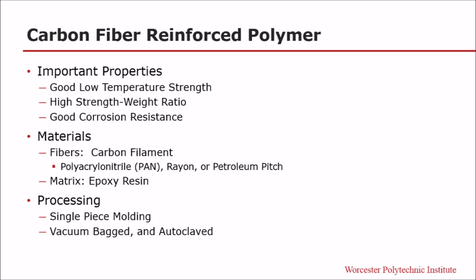They are usually taken and spun into filament yarns where they are chemically and mechanically treated in order to align all the polymers. They're then spun into yarns where they are able to be heat treated so that only the carbon atoms remain. This is known as a process called carbonization, where they're then able to be stored and further heat treated in unidirectional sheets that are able to be used in the composite. The typical matrix that is used in these composites are epoxy resins.